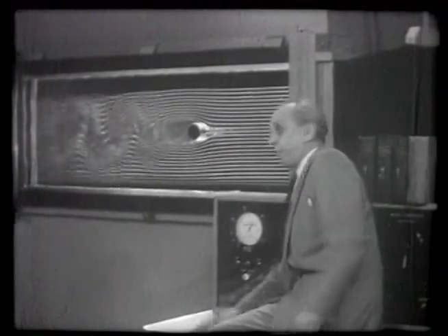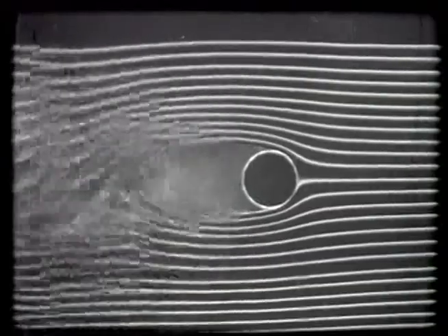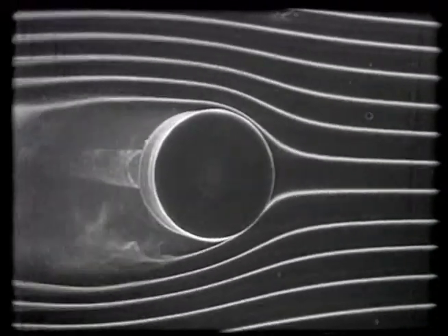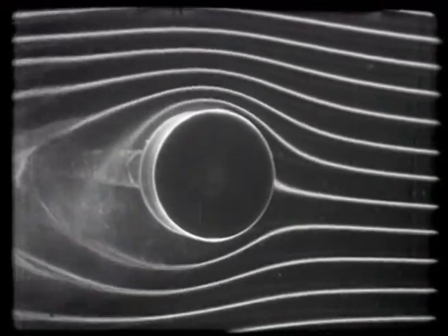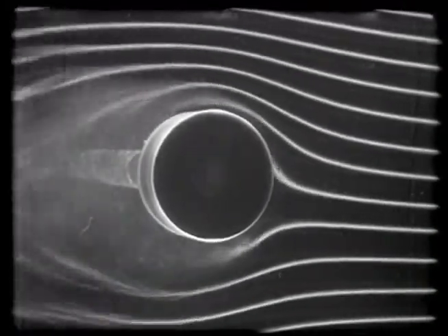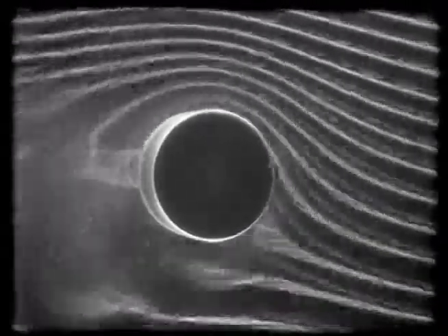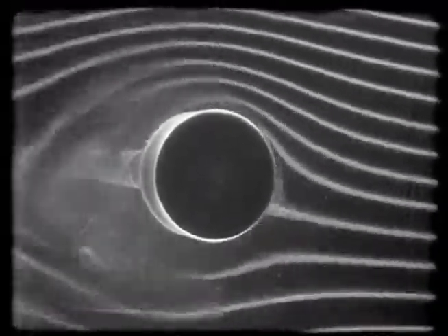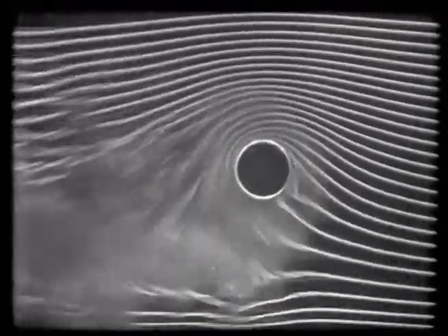Now we will begin to rotate this. I will go out of the flow field so that you can see it. Now we have the cylinder in the tunnel and we begin to rotate. Look at it. The more we have rotation, the more flow lines are pulled over the upper surface of the cylinder, and you see at once that our speed is very high above and quite low underneath the cylinder, which gives us a lift normal to the direction of the flow.